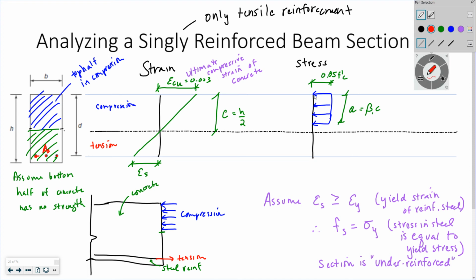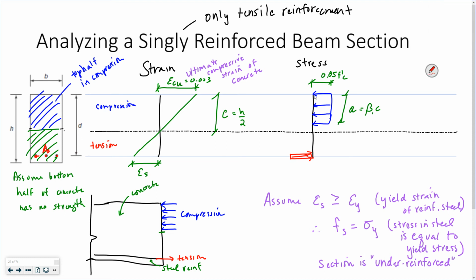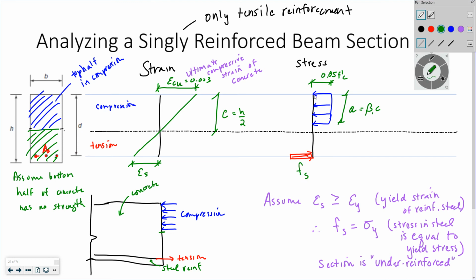And the stress in my steel, right? That's the tensile stress. Well, I just said it's my yield stress. It's the stress in my steel, but I'm assuming it's under reinforced, so it's actually, oh, I should have put that as an f. Change that to an f down there.